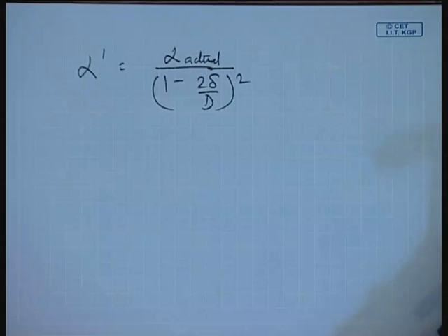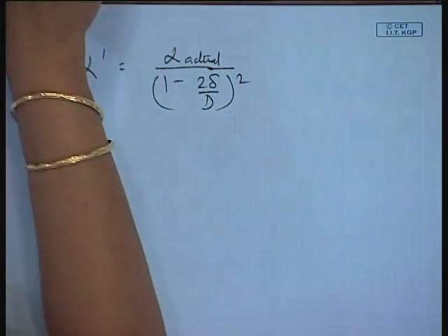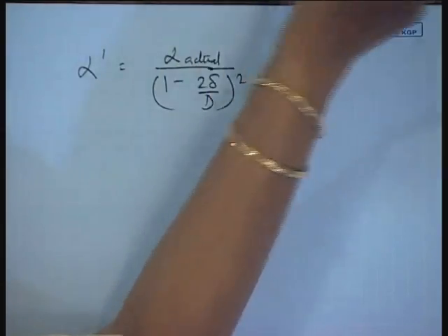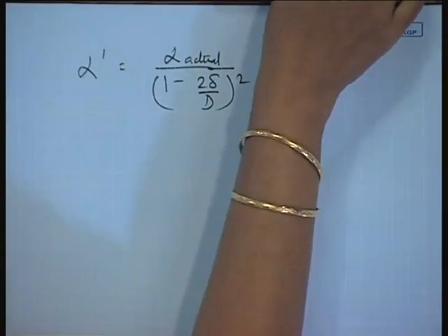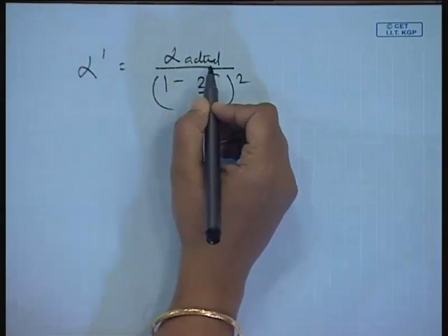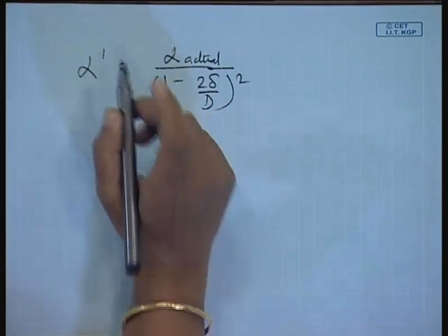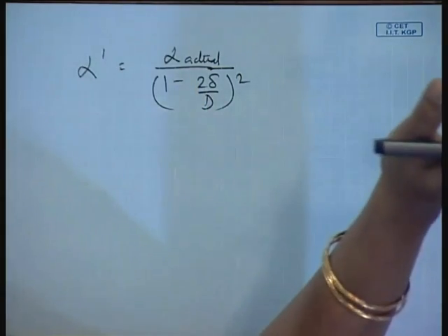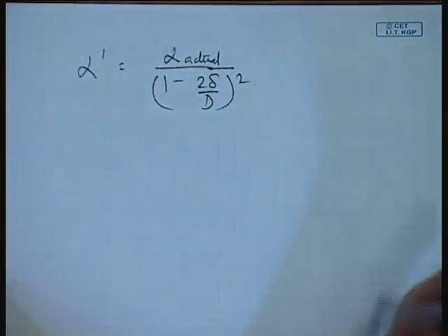Yes or no? You tell me whether you have understood this particular portion or not. Have you understood? Yes or no? It is clear? So, therefore, how to find out alpha under this particular condition? In order to find out the effective void fraction, not the actual one, you have to remember two things: since a good amount of liquid is now flowing as film, it is going to affect the liquid slug length here.